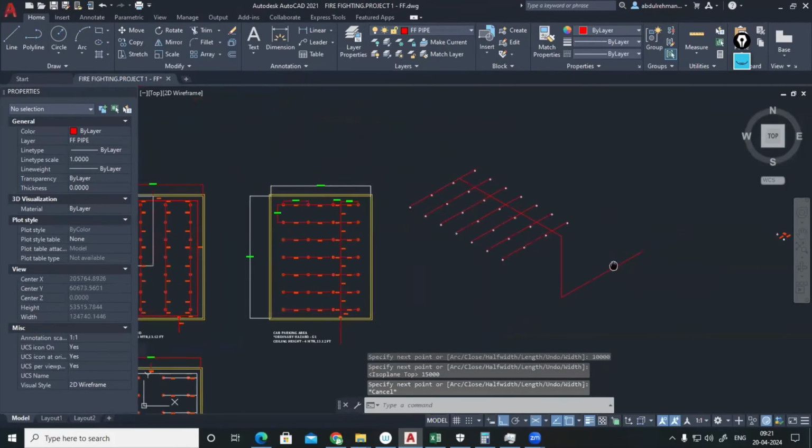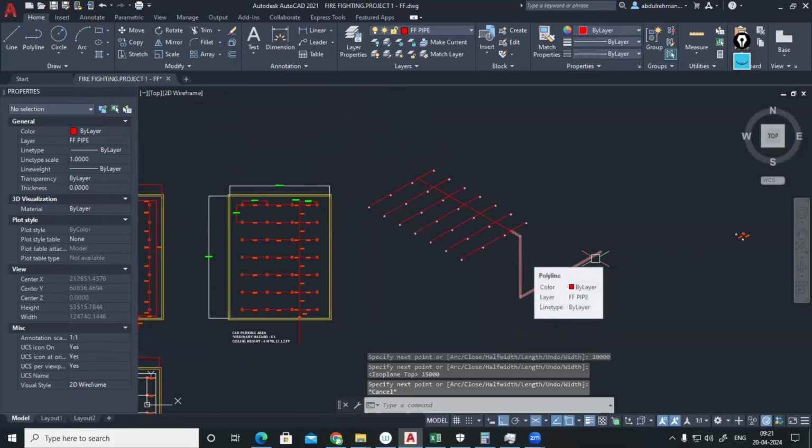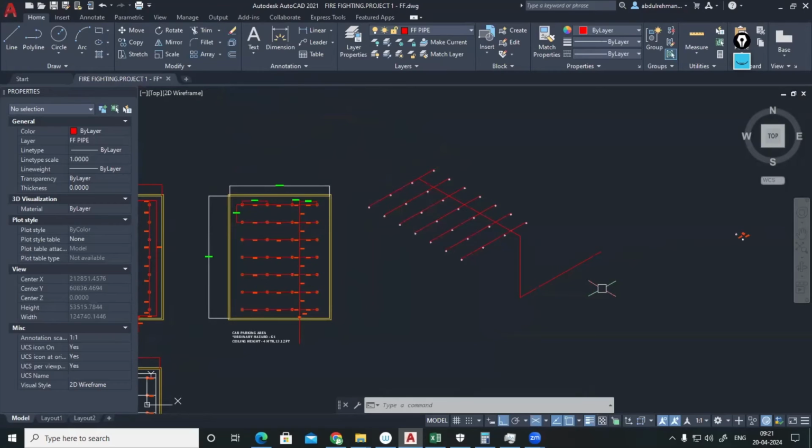In between this line, I'll have the standard pump connection, the pump suction line. If it is a negative suction, a foot valve will come, but normally a fire pump will be positive suction only. On the suction side, we will have a vortex inhibitor.